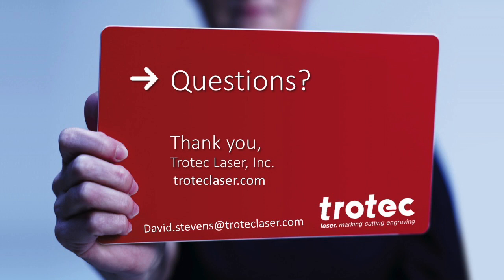Can PVC be engraved? No, we do not recommend processing PVC materials. PVC produces a harmful and corrosive chlorine gas when it is laser processed. So we do not recommend laser marking any PVC products or materials.